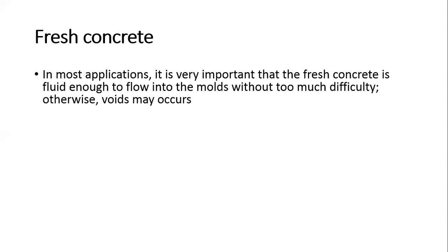So in fresh concrete, in most applications, it is important that the fresh concrete is fluid enough to flow into the molds without too much difficulty. Otherwise, voids may occur. What is the meaning of this? Suppose the concrete is not fluid enough, so when you put that concrete into the molds, it will create voids in the concrete that are harmful to the concrete and lower its strength.